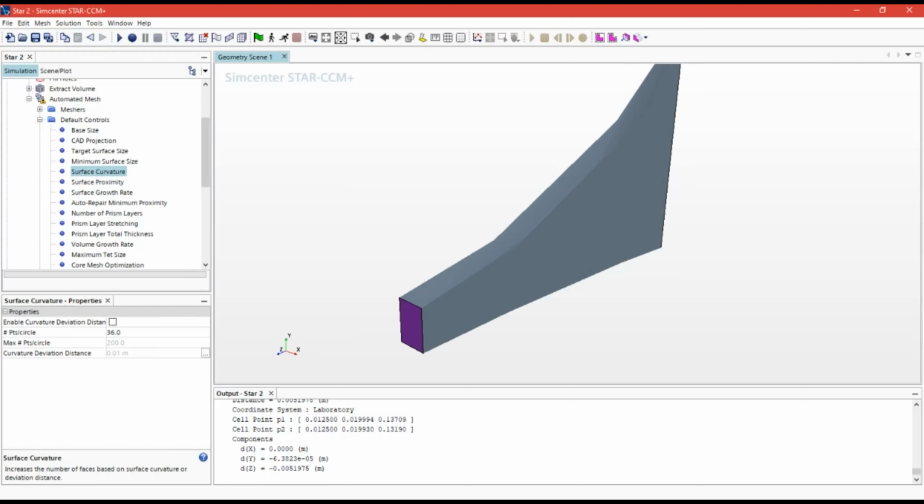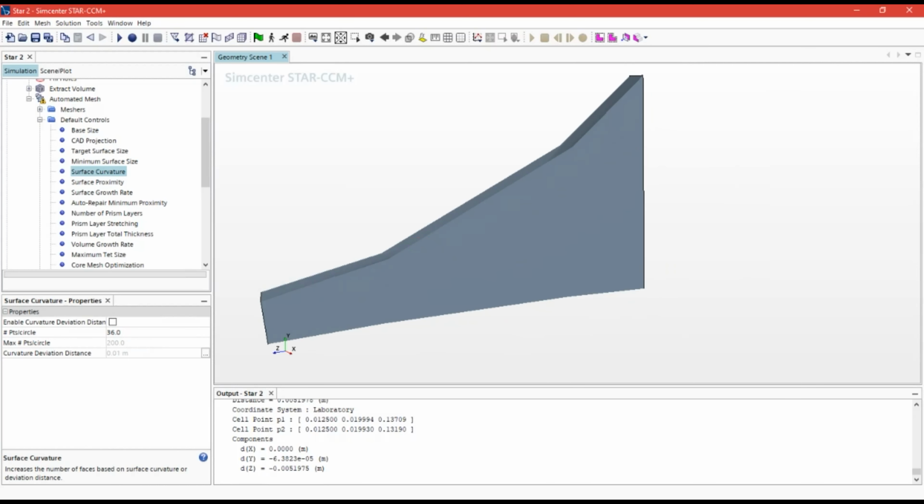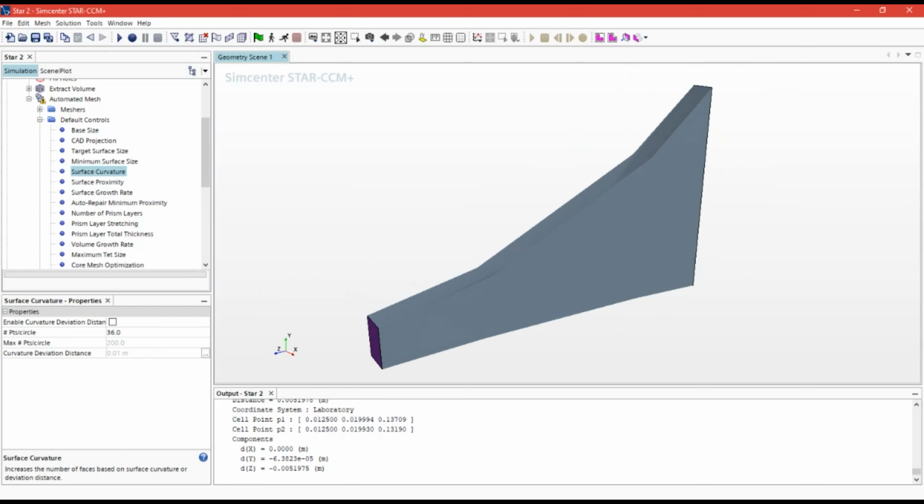You can just think about it. If you have 3 points in your circle, it's a triangle. It's not a circle. But if you have 36 points, it's probably going to be properly round. That's a fine default value. We don't even have any round surfaces, or actually, that is wrong. We do have this spline geometry here, but we'll just leave 36 points per circle as is.